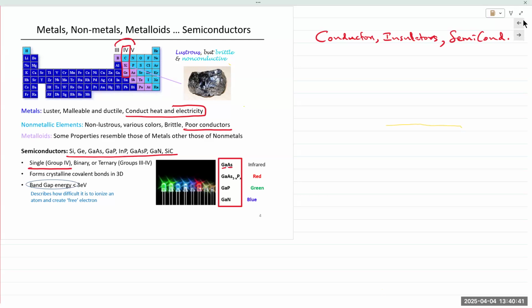That is what we use in fabrication of semiconductors. We have these glass masks that store patterns on them, and then we take a UV light source and stick our glass mask in there. Light is shone on it, and light passes through. We have our silicon wafers sitting underneath that mask. We coat it with photoresist material.